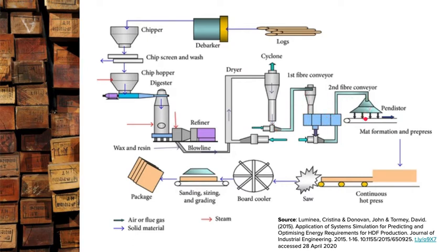and they're transferred across onto another conveyor belt, and they're put into a large mat. Okay, a large mat, so they're laid out like a big sheet. The big sheet is injected with a whole heap of glues, a whole heap of resins, which help to stick these fibers together. They are pressed really hard together between some metal plates. They're heated up, they're steamed, and they're really compressed into this really high density sheet of timber fibers.